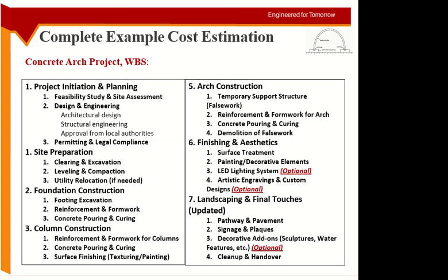Then you have the construction of the arch itself. Some temporary support is required for the arch because it's a curve, so you have to support it from all the sides. The formwork alone will not do the job. Then you have the reinforcement, pouring and curing, and then whatever false supports you have established, you will remove them. Then you have the finishing and the aesthetics: surface treatment, painting, any decorative elements, any lighting. If they want any artistic designs or something, you can see these things are optional.